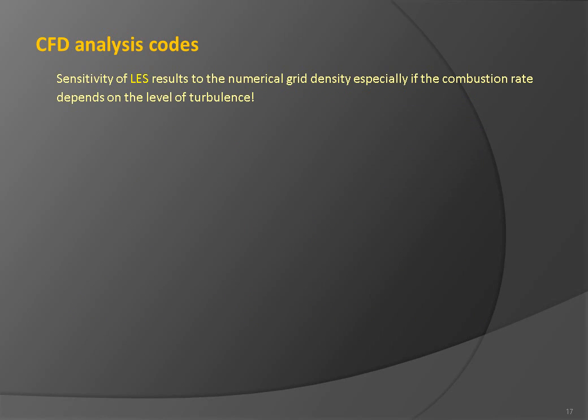But LES modeling results are notoriously sensitive to the density of the numerical grid. Using LES models on a numerical grid that is too coarse may lead to wrong results, especially if the combustion rate depends on the level of turbulence, which is mostly the case in environmental flows.